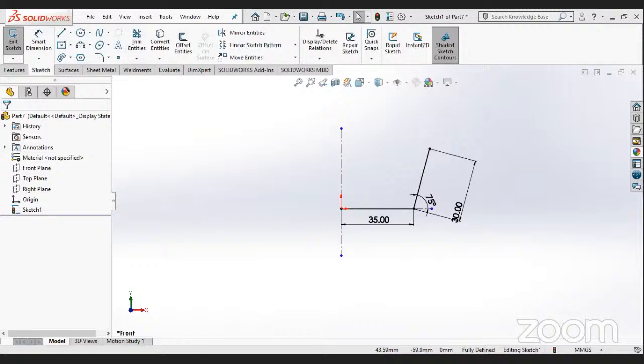And we'll start making the fins on the upper side. I'll just zoom for that. There are two dimensions. One is here and the other one is here. So from the down, as you can see here, the distance from outside to this line is 20 mm apart, and the distance from the inner hole to this point is 6.